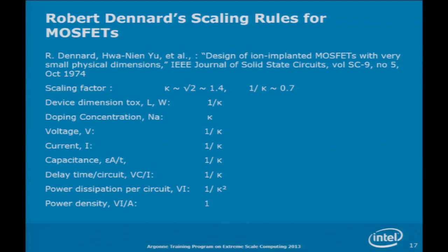Consumers would like more transistors, and that's another reason why you go to more cores, because one way that you increased the speed of processors in the past was not only increasing instructions per cycle, but also increasing the frequency. The frequency is roughly proportional to the voltage, but as you increase the frequency, you also increase the power. And without lowering the voltage, which Dennard scaling does, you can't afford to increase the frequency.